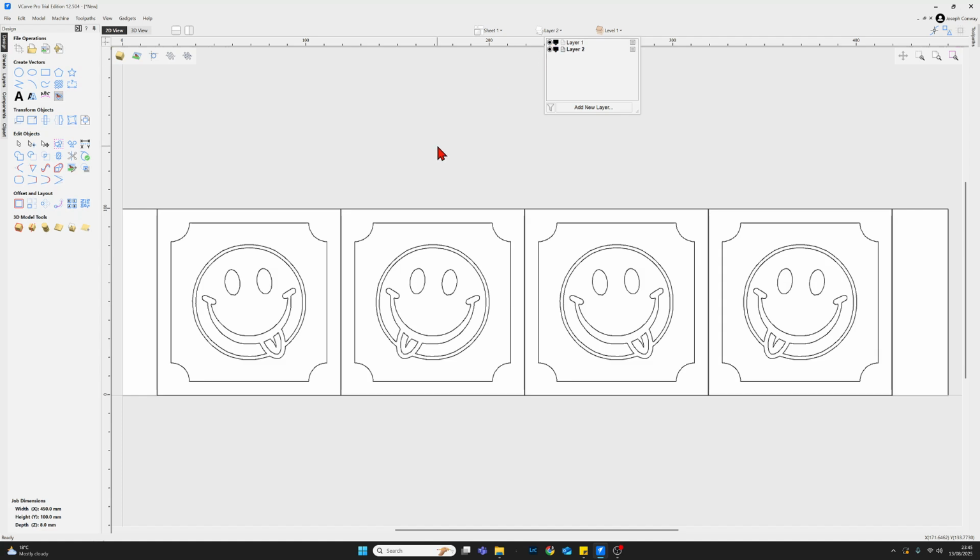And we're now at a position where we can start looking at some tooling. I'm just going to use one tool bit. I'm going to use a 60-degree VCarve bit on a 1/4-inch shank to carve all the bits on this, including the dividing lines. So just really to make this as simple as possible, everything is going to be done on one tool. So let's move on now and take a look at creating our toolpaths.